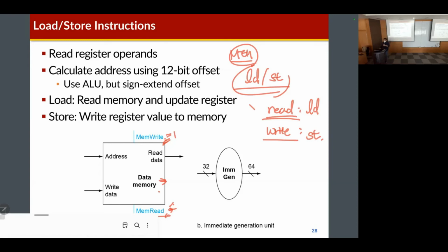The reason is that if we see the instructions, every instruction needs to read data from the register file. Right. So every instruction, like add, store, load, and also a branch instruction like BEQ, accesses the register file for a read operation.